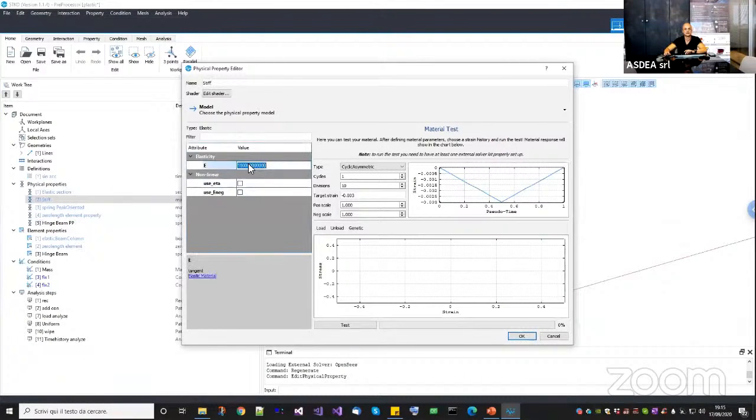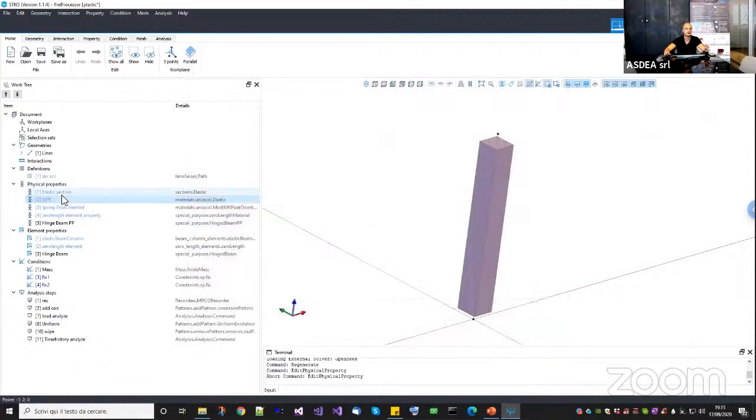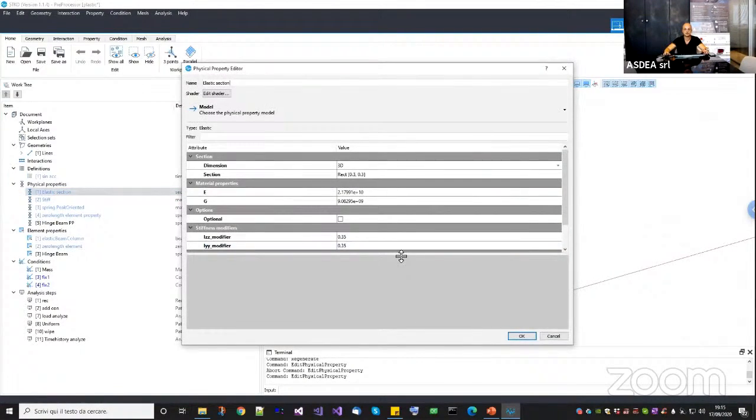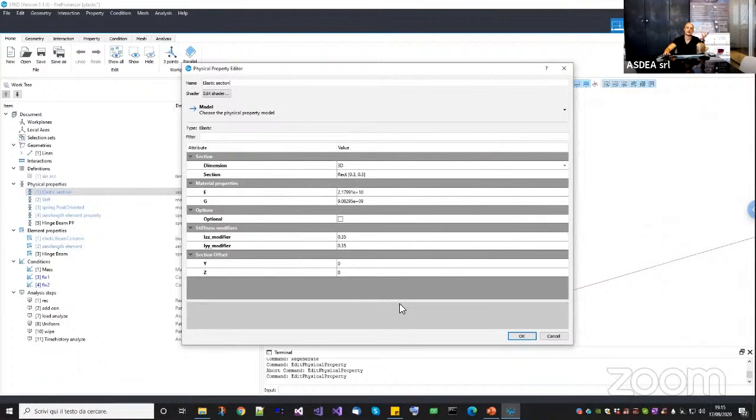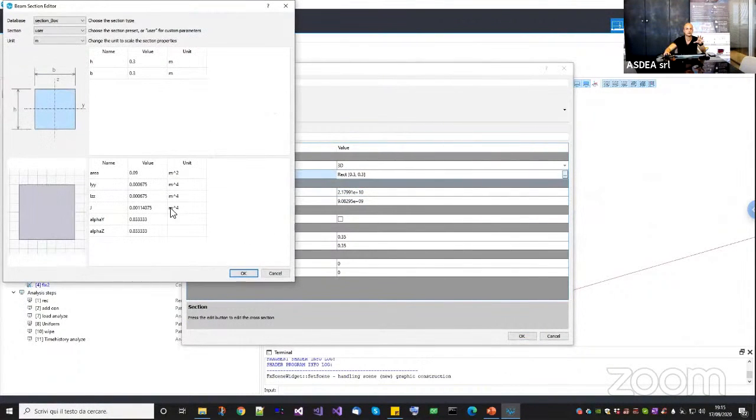The stiff material is chosen in such a way that it is a couple of orders of magnitude stiffer than the bending stiffness. Because here I need a stiff material to impose an equality in the other dofs. So how do you choose that number? Well, in this case, I have something to the power of 10 for the Young modulus, but then I have something to the power of -4 for the bending moment of inertia.